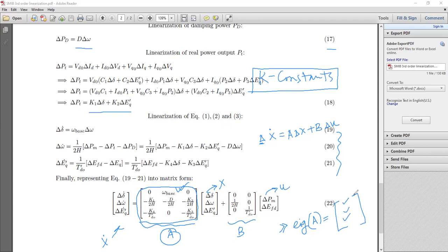So if these are the system poles, that is the eigenvalues of the system, that means if you plot them, and if all of these poles are lying on the left half of the S plane, this is sigma, this is j omega, and this is your complex S plane. So what should be the conclusion? If all the three eigenvalues of your system A matrix, calculated over here, lie to the left of the imaginary axis, what is the conclusion regarding stability? The system is stable. Excellent.